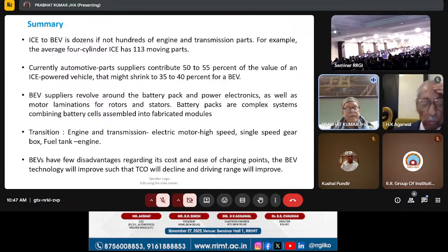And one thing is very, very important: whenever you charge a lithium battery, gentlemen, please charge on the principle of 80-20. It means for general use, you charge it to 80%. When you go locally around your city or somewhere, don't charge more than 80%, so your efficiency will be the maximum. And that 20%, never ever go below 20% charge.